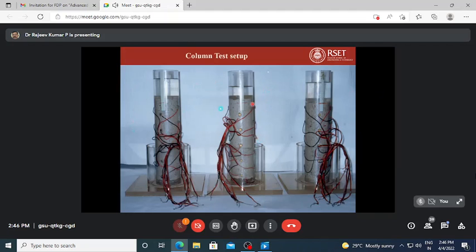And this is on the sideline of the centrifuge test. We have done some column tests also. These wire leads are actually connected to the soil contaminant detector, which was developed. I have already mentioned that in the previous slide, and it is connected to the soil sample. This is a typical soil column, which has a 30 centimeter height and an impoundment or reservoir of around 10 centimeter height. And in some cases, it is less. You can see here, in some cases the reservoir height is smaller than the other two, because the leaching of contaminant took place.